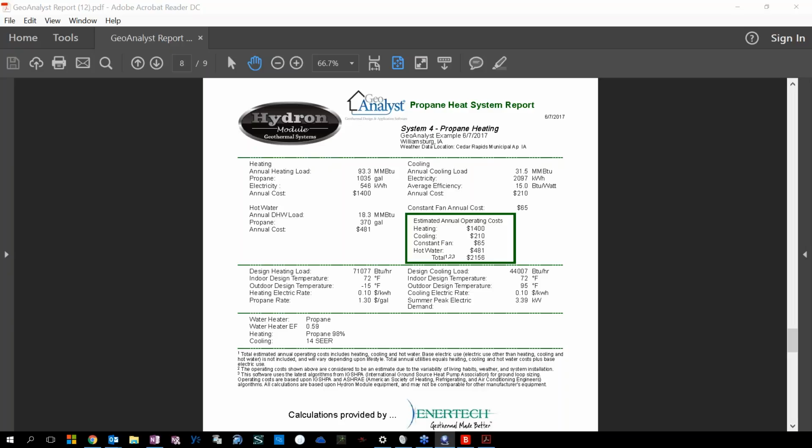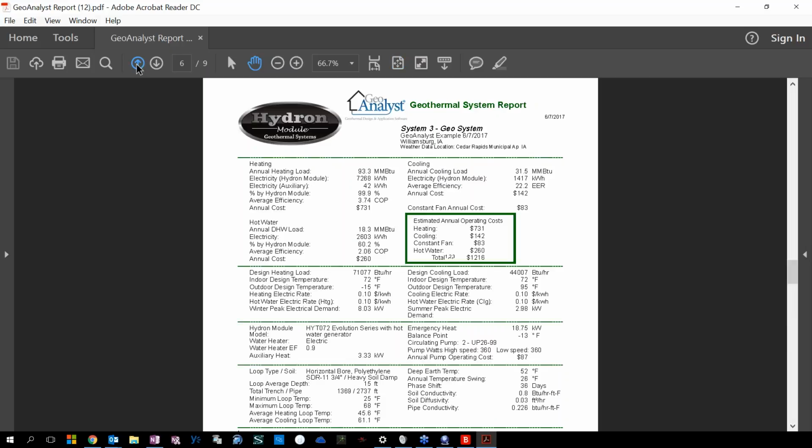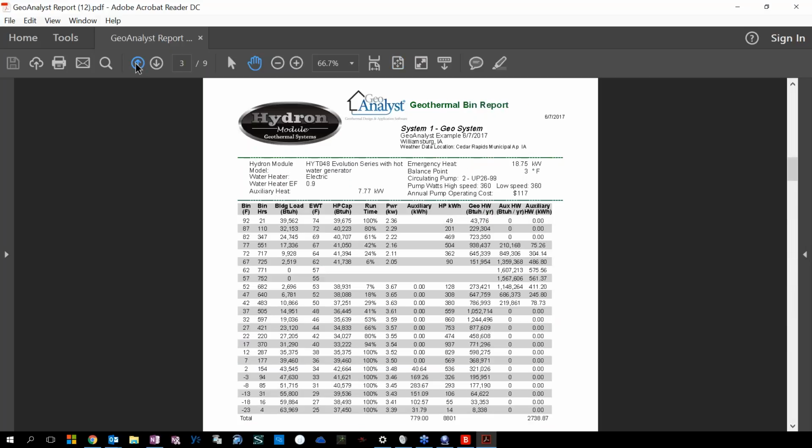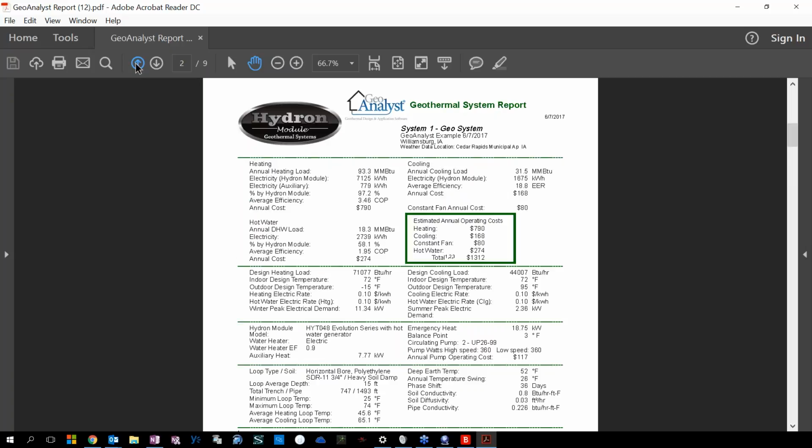The question, just for everybody, is when we go to apply for our geothermal permits here in Alberta, we have to show that the heat pump meets at least 85% of the capacity of the heat loss. So even a 4-ton, if I was looking at GeoComfort GXT in the manual, I think it provides something like about 38,000 BTUs at 30-degree incoming water temp.